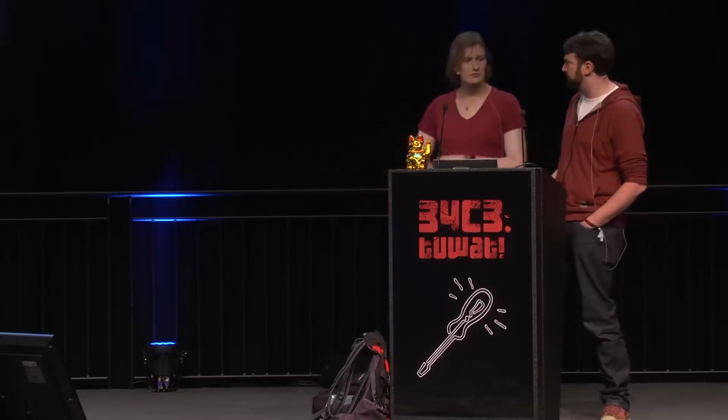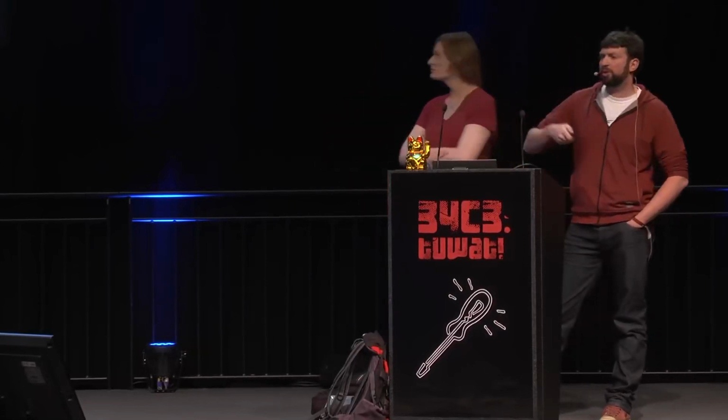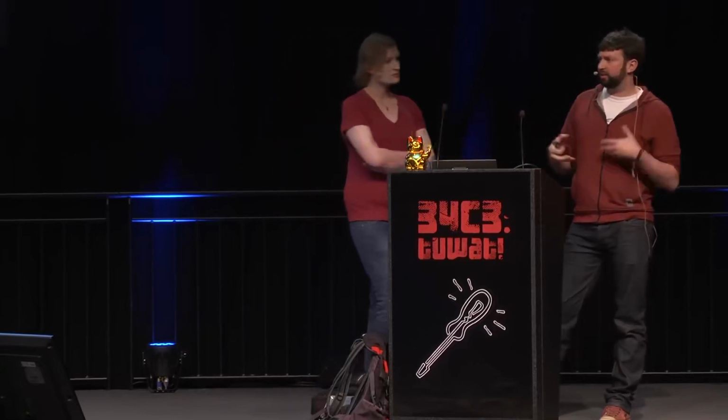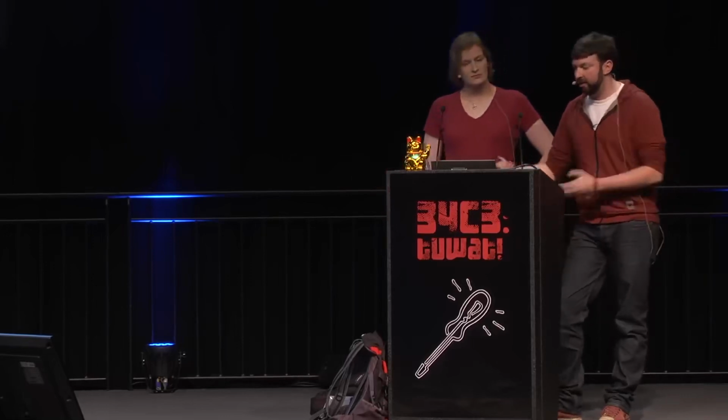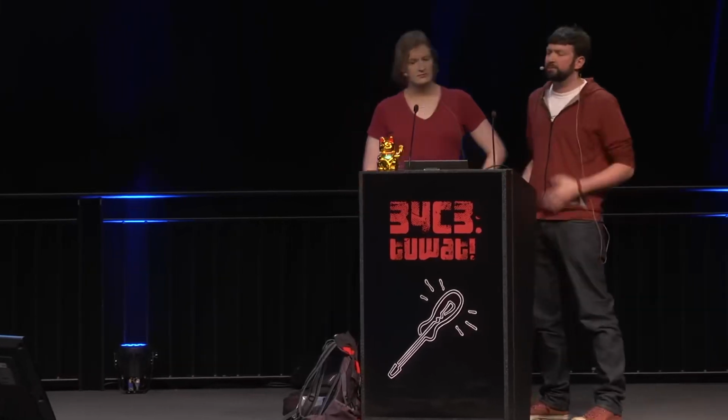Yeah, the goal is that we're not trying to bring the amount of hardware hacking you have to do down to zero, because that's virtually impossible with this technology. But we're trying to take it from, I've got to spend 2 weeks designing a custom board, sending it off to a PCB fab, getting it back, and building this thing with a couple parts, to a couple of hours. Okay, well, I've pulled off all the decoupling capacitors, and now I've hooked up my hardware to it. Now let's go and see if we can glitch it. So we're just trying to reduce that turnaround time and make it easier, especially if you don't want to have to design hardware.